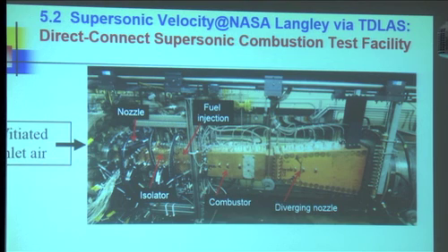So this combustor is the place where they would put the engine, and then they would diverge. This isolator is this kind of entry-level section where we're going to make our measurements. The nozzle was the exit of the heater, so that's the thing that prepares the air to simulate flight at some Mach number. I think they were testing at Mach 5 and 7.